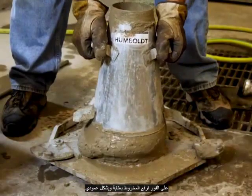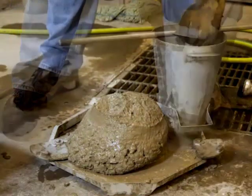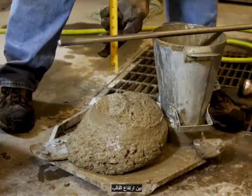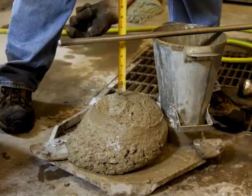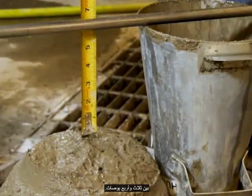Immediately lift the cone carefully and vertically to separate it from the concrete. Then determine the slump by measuring the difference between the height of the mold and the height of the concrete. The slump of this mixture should be between 3 and 4 inches.